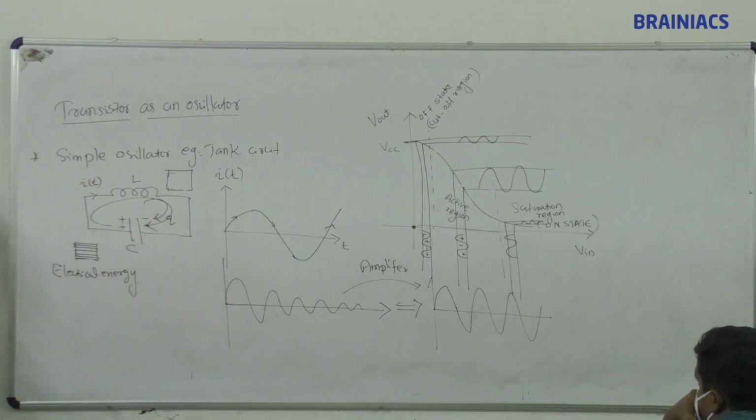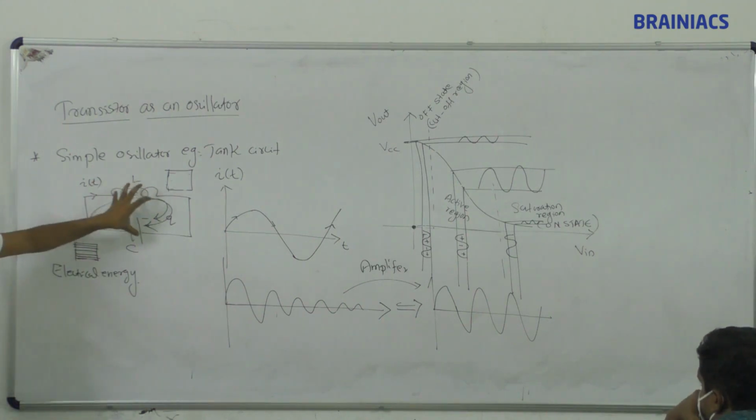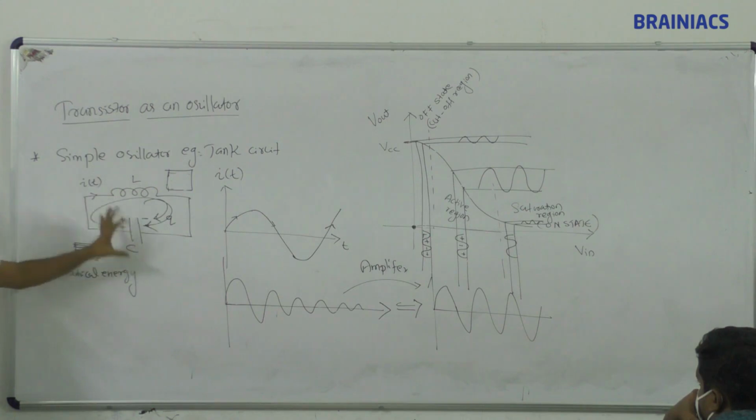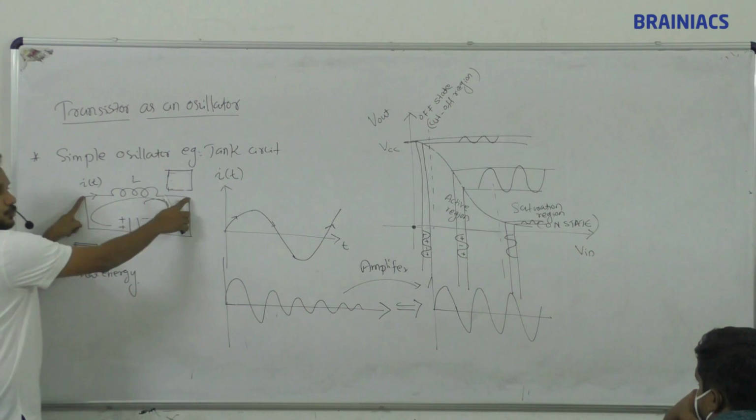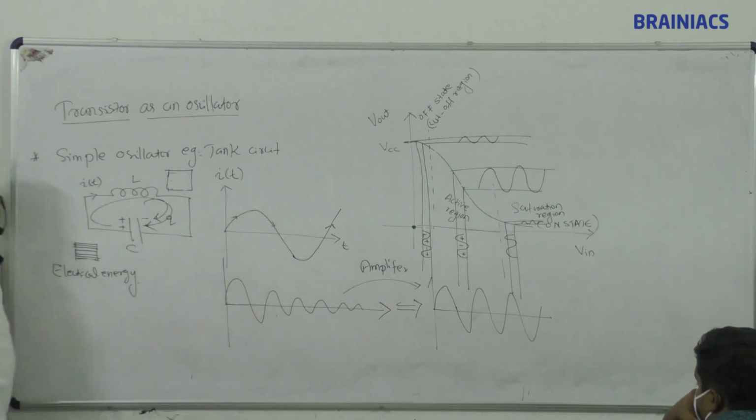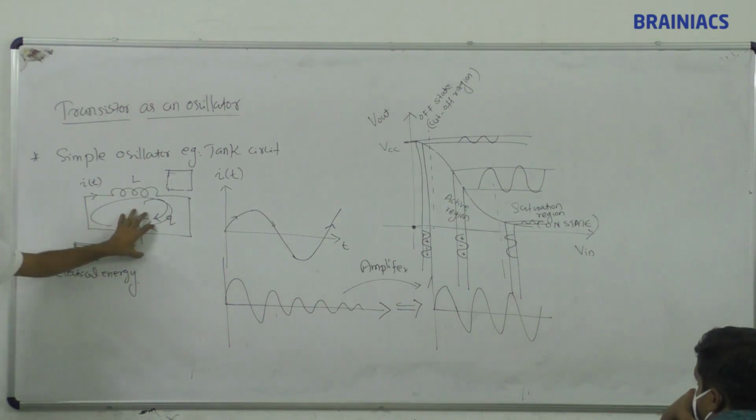An undamped oscillator signal. So simply it's an oscillator, an LC oscillator, and this LC oscillator has no input signal. Initially a fully charged capacitor will be placed here. That is over. Now if you take the output between these two points, you get a signal like this. Understood? So the oscillator has no input. If the oscillator has no input, how? Okay, initially I have given some charges.